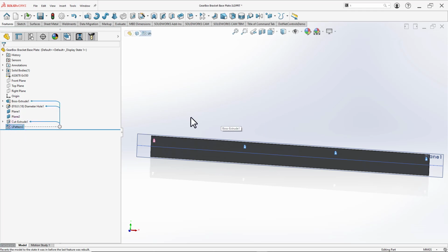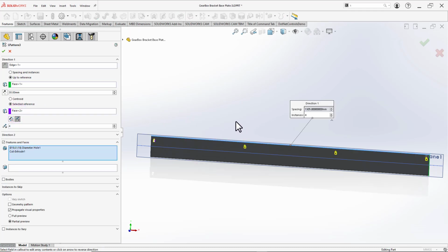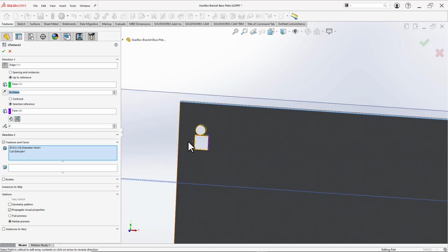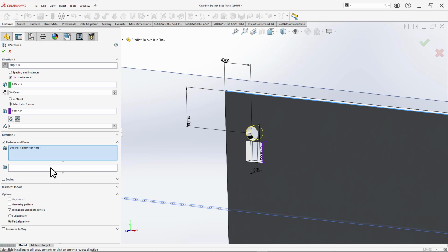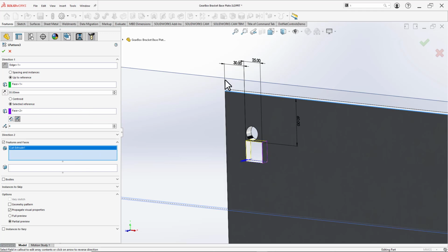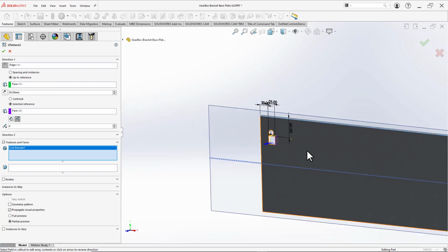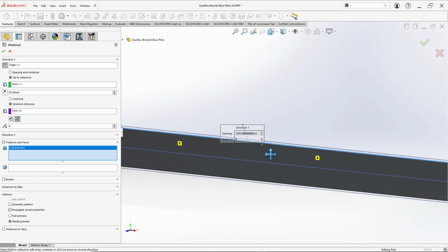Now, that's not all. There's more to it. Equations. We can use equations in here. So, say, you see this 30 millimeter? Where did I get it from? Well, I knew 30 millimeter is what I want because that's the distance that I defined here. Just allow me to delete this. Yeah, so I knew that this face is 30 millimeter away from that line there. So I just simply entered 30 millimeter here and then took that as an offset.